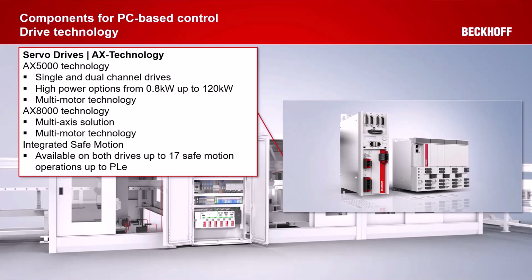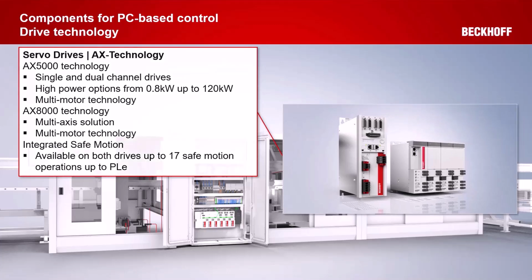And a very important aspect is the integration for safety. With this technology, we offer 17 safe operation modes up to a safety level of PLe or PLd, depending on what you need. Each one of these drives has a single and a dual channel aspect to it, and they're very easy to integrate directly into your control system.